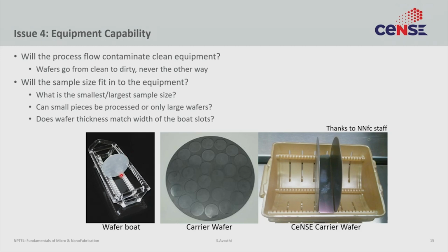So what can you do? Well, you can make a makeshift sort of board like this, but for that you have to actually create this piece of silicon and actually clean it during your cleaning step. So if you think of this problem in advance, you will clean all these accessories and create this mini boat that can hold a smaller sample. But if you don't think about the problem, then you do all this cleaning, you go to the tool, you're ready to do your deposition, and suddenly you realize you can't do that. And that wastes a lot of time, it wastes a lot of energy, and it's very demoralizing. So again, think ahead, think ahead, think ahead. Devil is in the details.